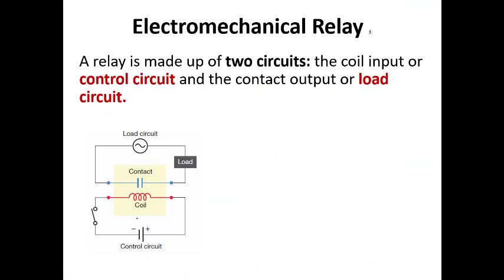All right, so here is another example of an electromechanical relay, maybe with a little bit better picture. Here we have a voltage supply. Let's say that it's 10 volts, just so that way we have some sort of reference. And then let's say that this time we have 200 volts AC. So the first thing that we want to always remember is that there's two states with an electromechanical relay. There's the control circuit, and then there's the load circuit. And they operate on different voltages, and there's different wires, different wire sizing, all of that.